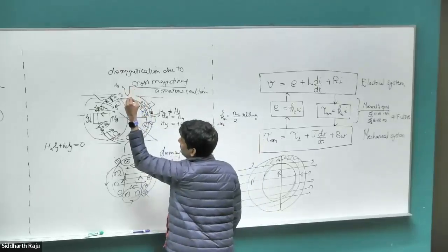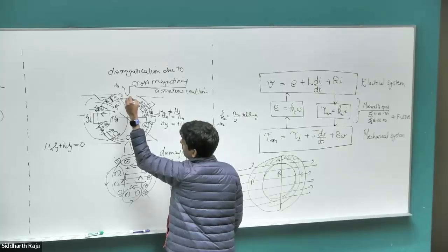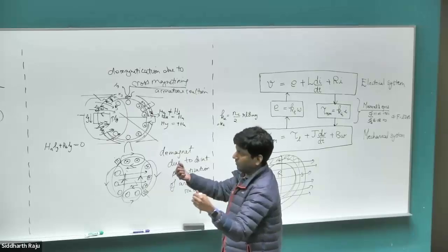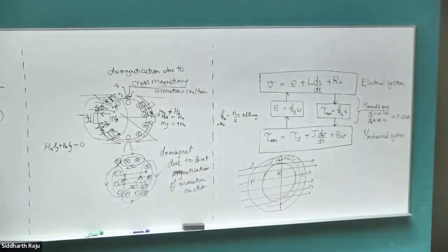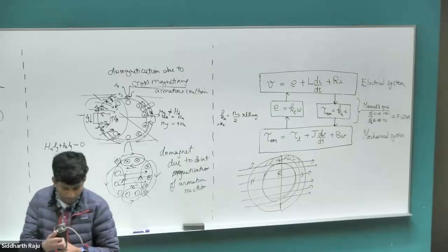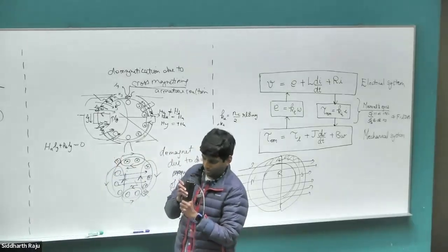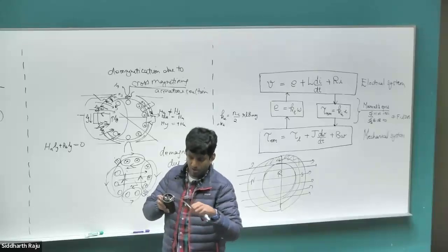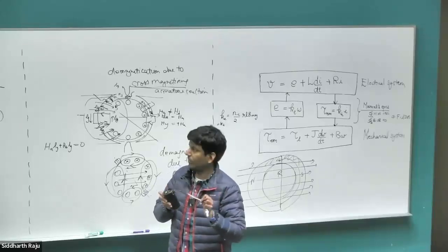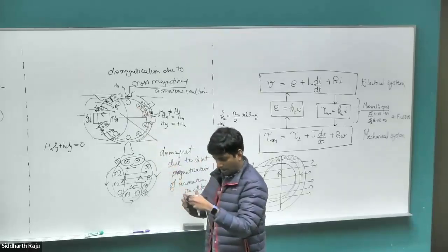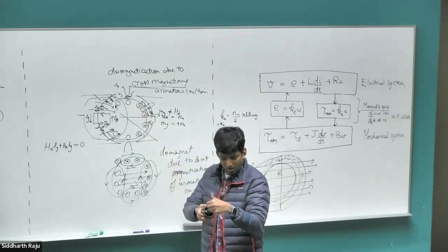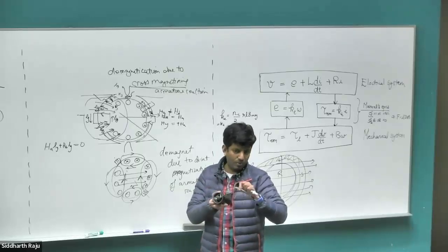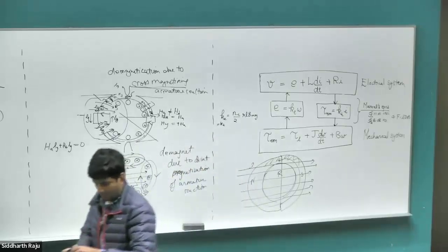So you have the wire coming out from the brushes of this motor, right? Typically, these are the two wires that come out in the DC motor that we have. So when we have this motor here, this does not have an interpole, nor does it have a compensation winding, which is the other method. If you look at this, the brush and the wires are directly coming out from the brushes. But in this case, there will be a wire that comes out from here. There will be a protrusion here on which there will be a bunch of windings. And then that is the one that will come out as an external wire when we have an interpole compensation.